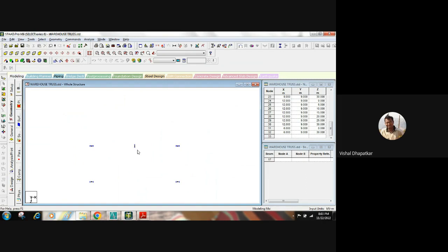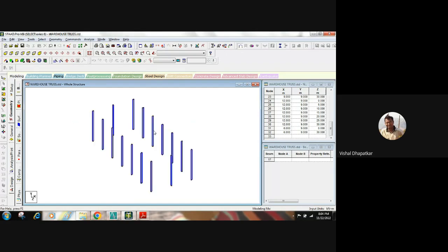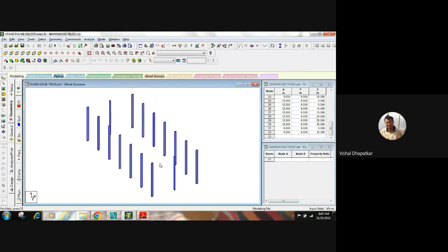So that's why, when we calculate, slenderness is calculated by the square root of I by A, right? Based on that, we calculate the slenderness. So once we place this axis in this direction, it will not have any tie for the complete length of the member. So in order to have less slenderness in this direction, we also rotate this column so that its compression capacity will not get reduced. So this is about the column orientation.